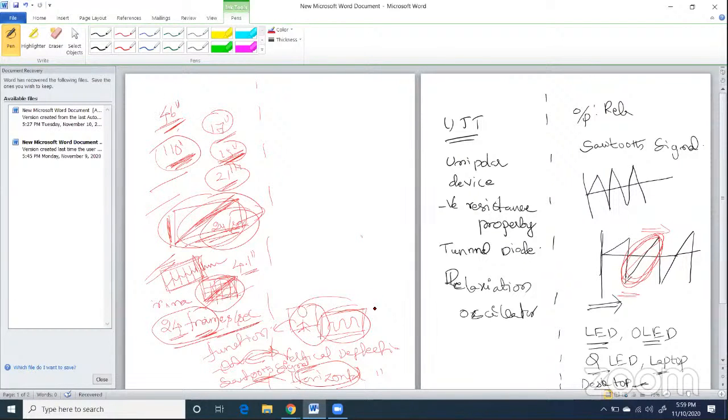If you keep the time slot knob of the CRO at zero, then you cannot find anything, simply a dot or a simple straight line. Now, if you rotate the time slot knob in the clockwise direction, then slowly the waveform sweeps across the screen like this. We can find this experiment practically also. You can do it in your EDC lab or IC lab or any other labs in which we are using the CRO. So this is the most important application of the sawtooth signal.